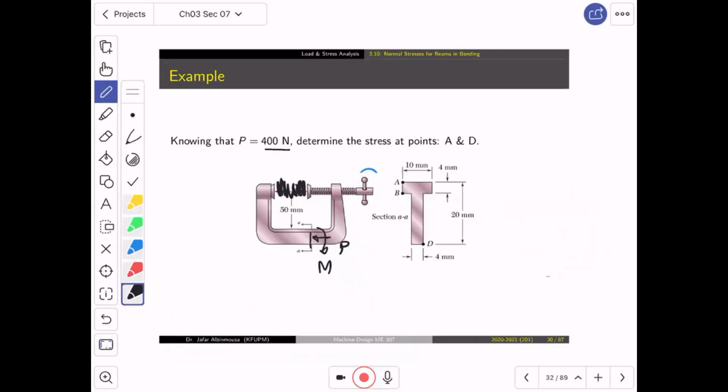So this is what I was saying. You can look at the problem in another way. Remove the forces here, just ignore them. Move the B down with its moment. When you move it, you must compensate with a moment. And this is it. You have a force and a moment. I was saying you can think of it this way: you don't want to analyze the section here, you want to analyze it here. So move the force to the cross section and substitute the moment.